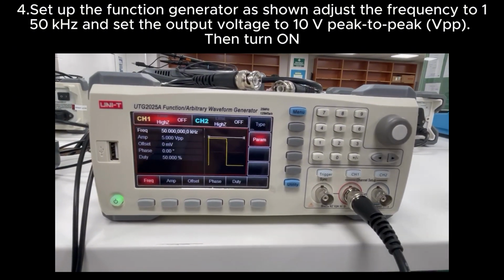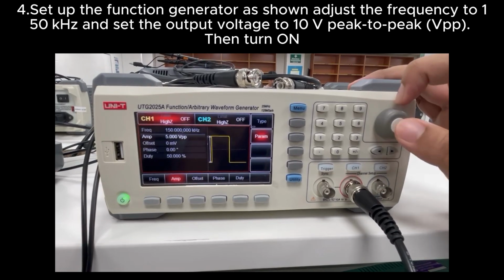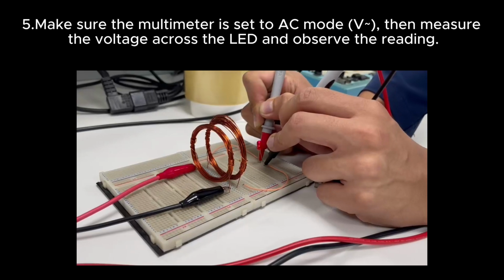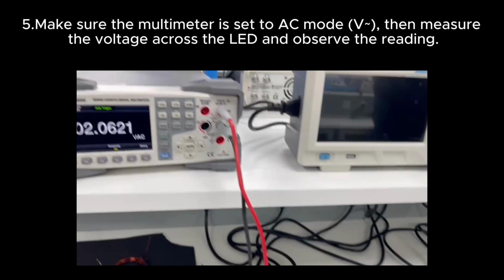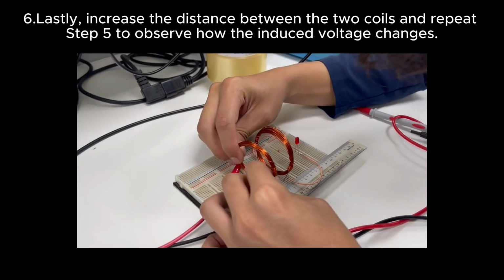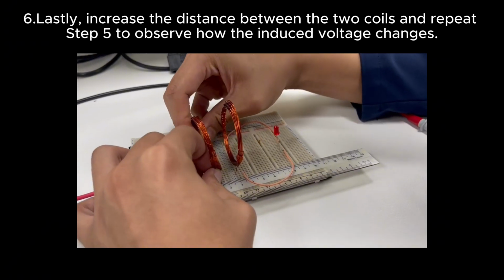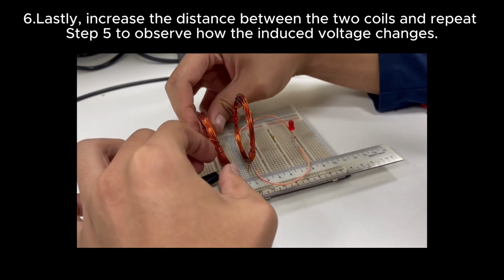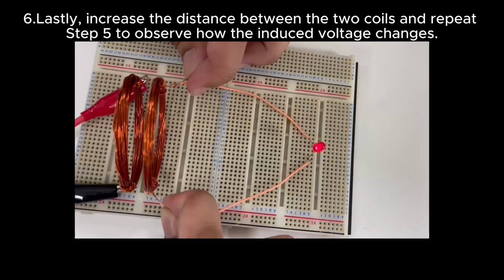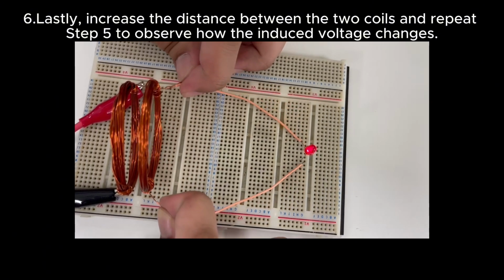For the fourth step, set up the function generator as shown, adjust the frequency to 150 kHz and set the output voltage to 10 volts peak to peak, and then turn on. For the fifth step, make sure the multimeter is set to AC voltage mode, then measure the voltage across the LED and observe the reading. And lastly, increase the distance between the two coils and repeat step 5 to observe how the induced voltage changes. As the distance increases, the LED brightness decreases. Conversely, the closer the coils are, the brighter the LED becomes.